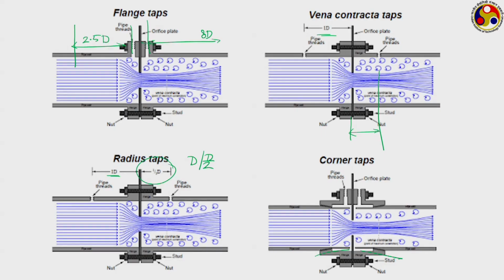So, this is about the orifice meter. Orifice meter is a very easy configuration, as we can see. We just have to introduce one orifice into the flow channel, and then the pressure drop across the orifice is going to give you the measurement of the flow rate. However, in case of orifice, as there is a drastic change in the flow dimension or pipe dimension, the fluid has to adjust quite a bit, thereby creating lots of disturbances and vortices formation.